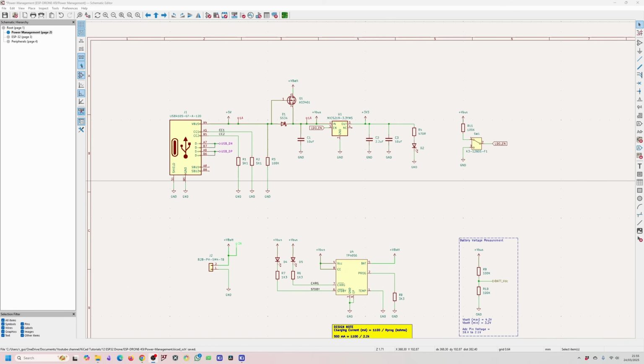So assigning a net class basically allows the PCB designer to make sure that they are meeting those requirements for the tracks. Now, it is your objective as a schematic designer to inform the PCB design and inform anyone looking at the schematic of the design intention and the characteristics of the data lines and the PCB itself. Now, let's say we have another line, as you can see on the schematic now, we have a VBAT line.